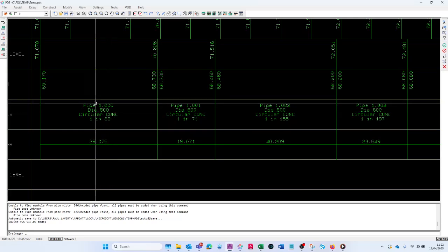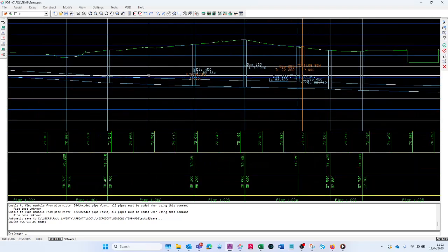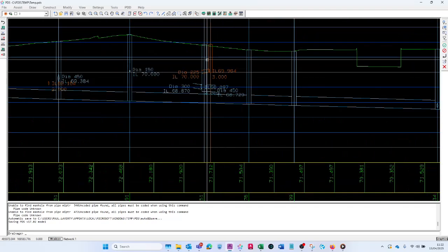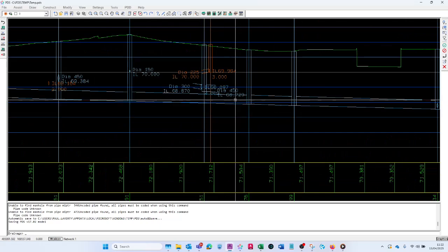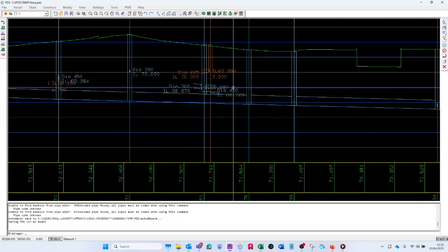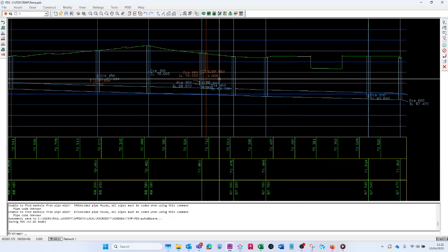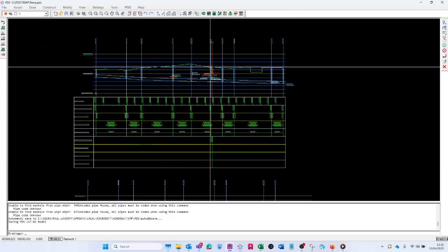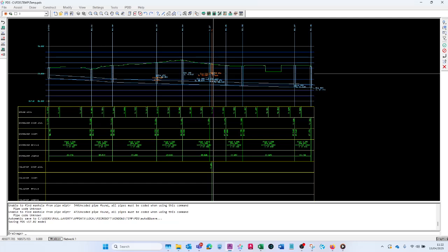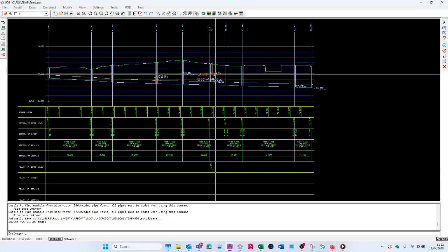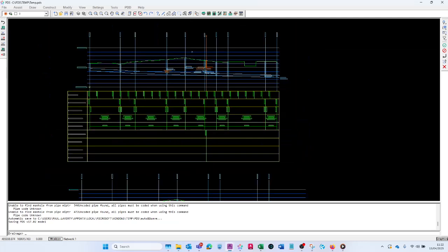We get the pipe code here, but we don't have it up to there because look, it's getting a bit cluttered. If that pipe code is on that, it'd be clashing with this information. So that's why I had the pipe code in that part there, and that's how you can add specific manholes to the chamber if you want, to the profile if you want.